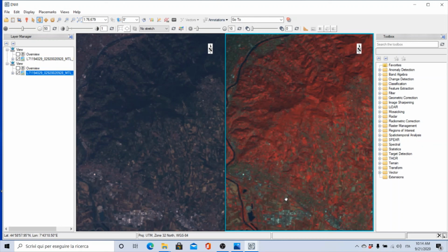I think something related to the position of particular features, but we also started to mention the fact that using different spectral bands, and parts of the spectral bands that are not sensitive to our eyes, we can extract, simply by viewing the image, some information. Like the fact that in the false color composite, when we associate to the red channel of the visualization, for example, the near infrared, we can notice that whatever is red is connected to vegetation and whatever is very dark is connected to water.